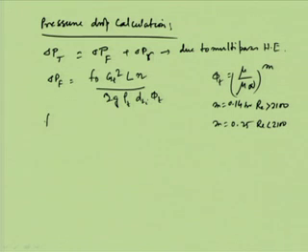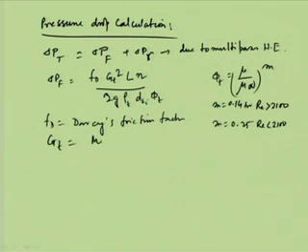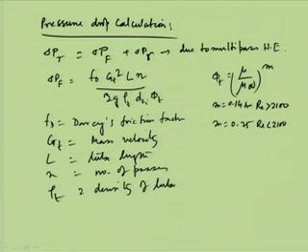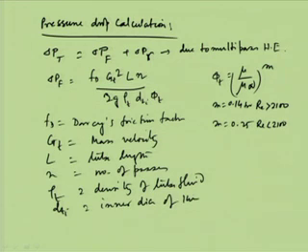And then here Fd is Darcy's friction factor, GT is mass velocity, L is tube length, N is number of passes, g we know, and rho T is the density of tube fluid, and dTi is the inner diameter of the tube. So, these are the terms, and g we know is the gravitational acceleration.